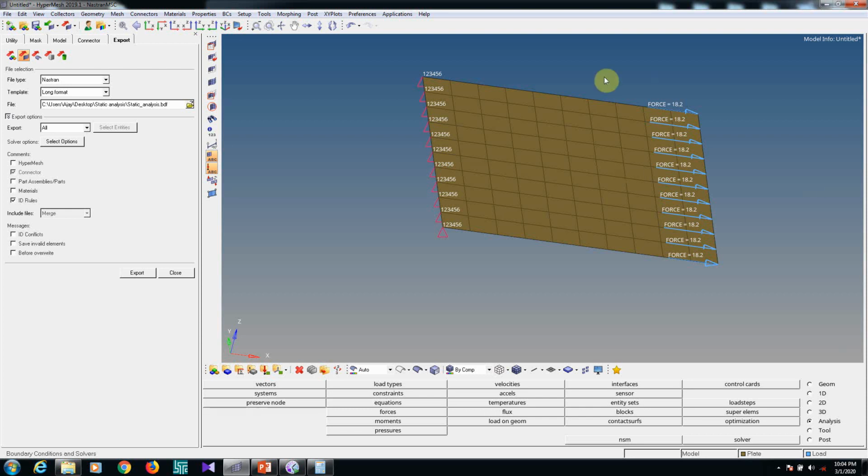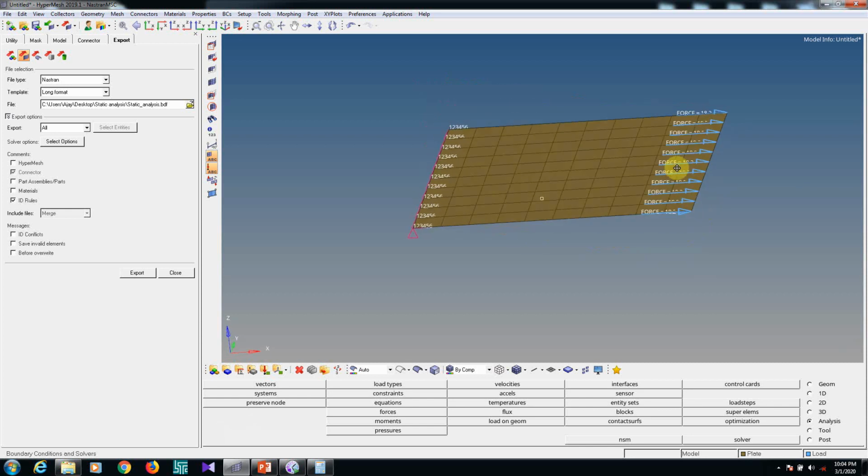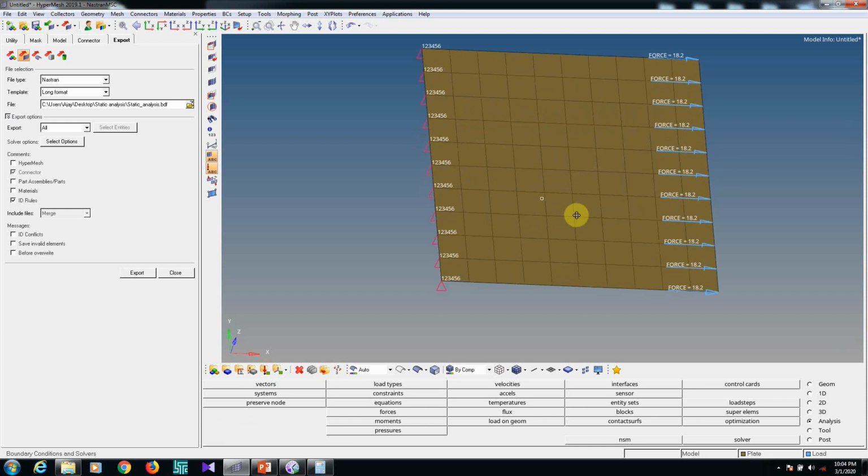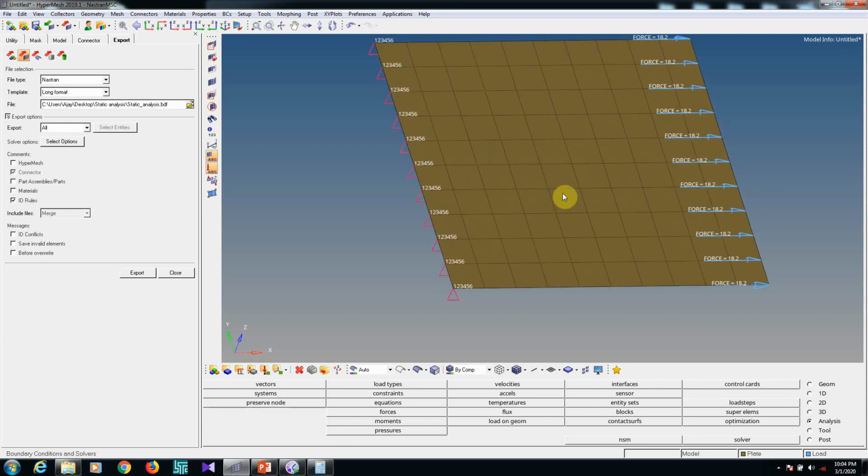If you are keeping only two elements or one element, because it is a regular cross section, right? If a complex feature is there, it has an effect. That's why wherever complex features are there, you need to do fine meshing, and in the remaining area coarse meshing. Specifically, if you want to carry out a stress based structural analysis, you need to think that deciding the element size plays a very important role.